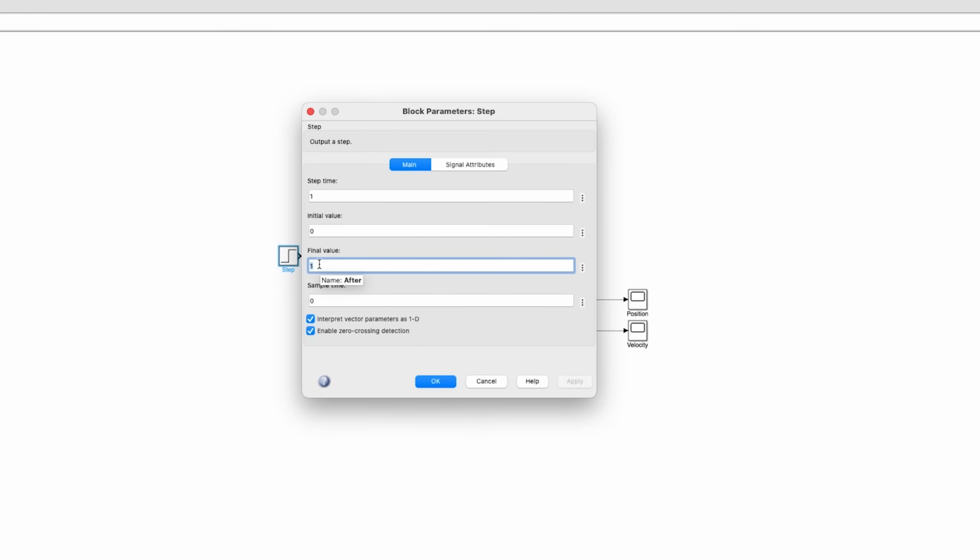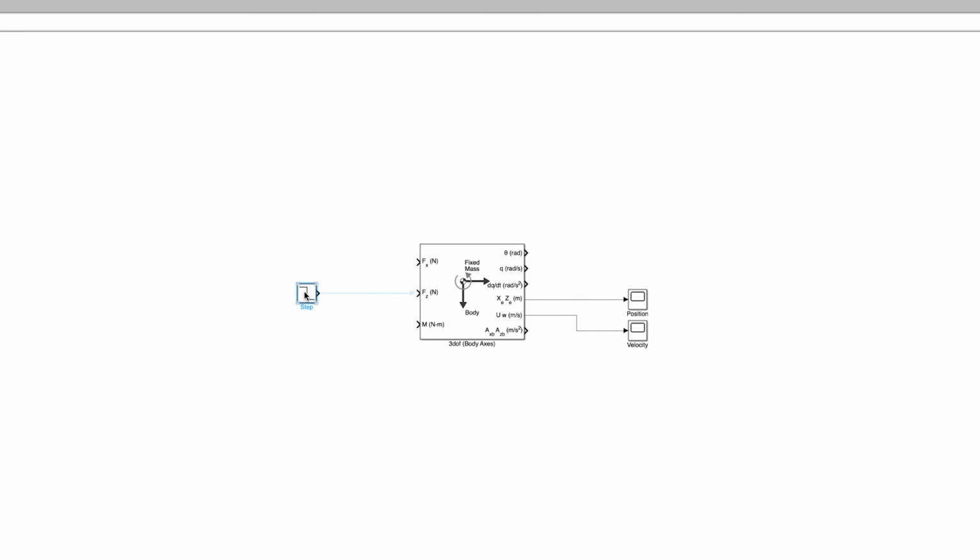If we're using an F44 engine, we should start with an initial value of about 44 newtons, that's the average force of that engine, and our final value should go to 0 when our engine burns out and there's no force. And for the F44, that occurs at about 1.8 seconds. So we have about 1.8 seconds of burn. We can plug this into our Z force, and then let's run this.